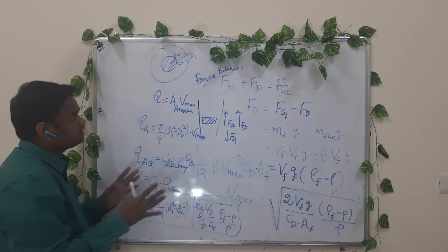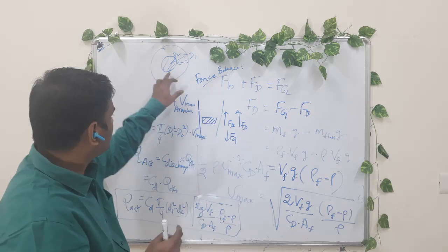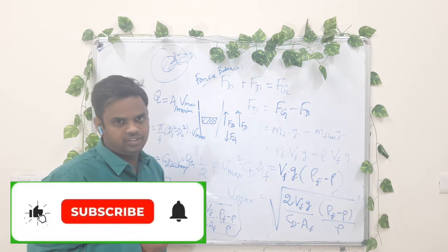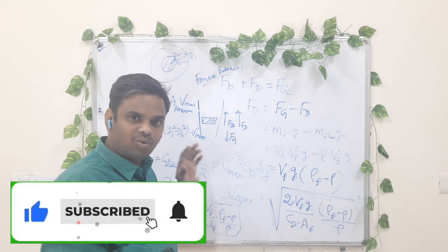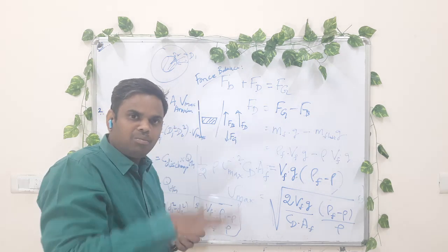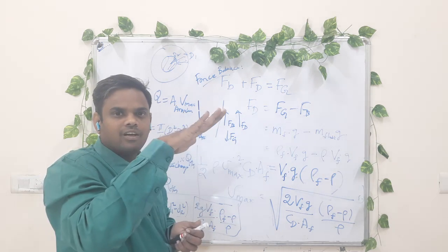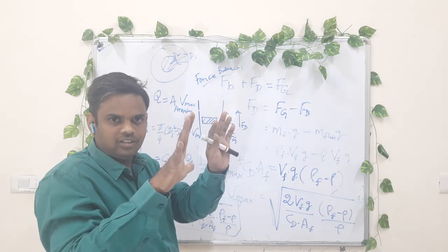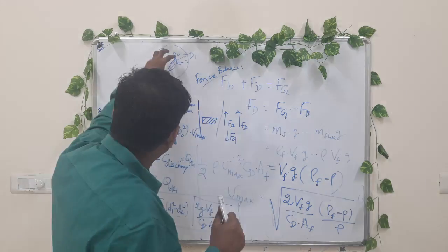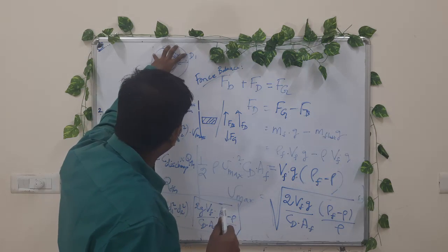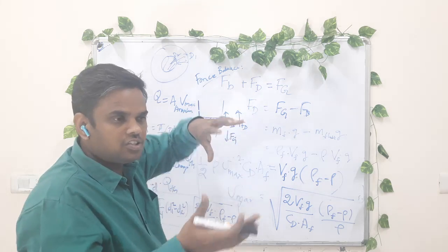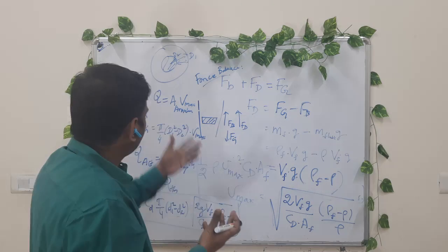If you look at the cross section area, it is similar to an orifice. So we can say this rotameter is a variable orifice meter. In an orifice meter, you have an opening whose diameter is fixed. Here also we have a float, and the annular opening varies depending upon the position of the float. It is similar to flow through some annular region.